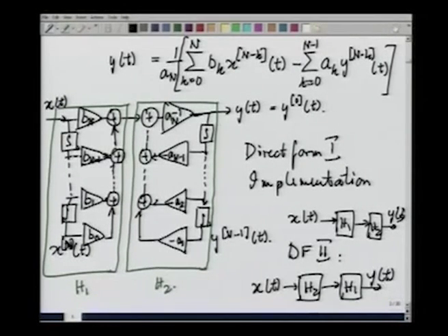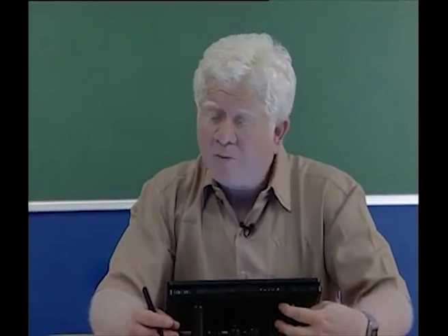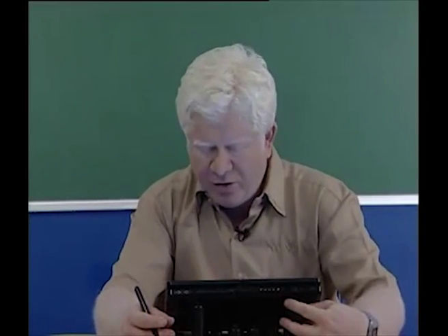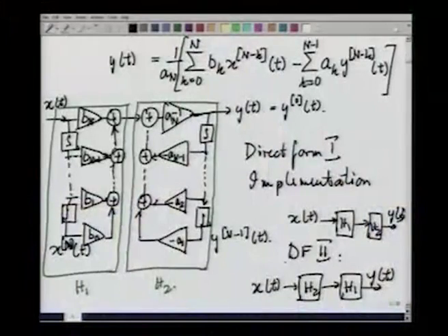with of course also implementing the savings that you get by collapsing parallel sets of integrators into a single set of integrators, into a single sequence of integrators. That is all you need to do to get this direct form 2 implementation of the same system.